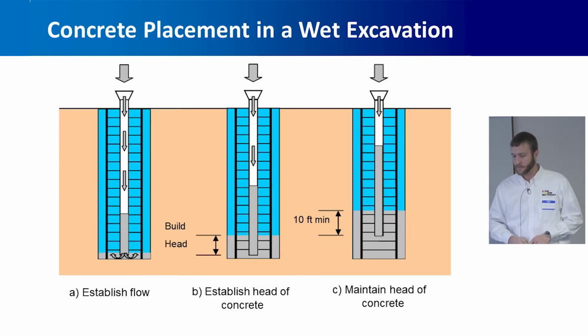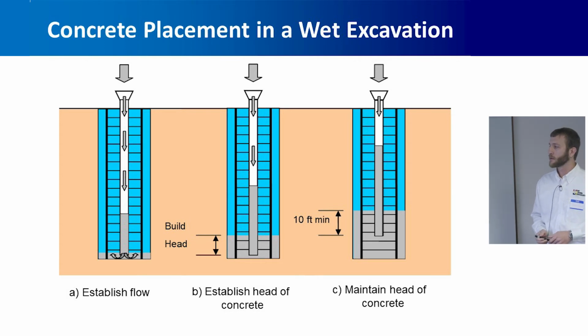Concrete placement in the wet. We want a good continuous pour from the bottom up. Like I say, the theory here is we're going to try to keep as much poor quality concrete and laitance and debris on top of that concrete and let it ride to the top.